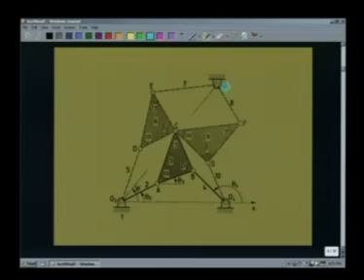Consequently, if we fix that point O, the point which was not moving, with the fixed link by putting a hinge, we convert this hinge at O to a higher order hinge connecting three links, namely 1, 7 and 8. As a result, now we have an assembly of links where there are three 4-bar linkages, one 4-bar linkage consisting of 1, 2, 3 and 4 with the coupler point at C.